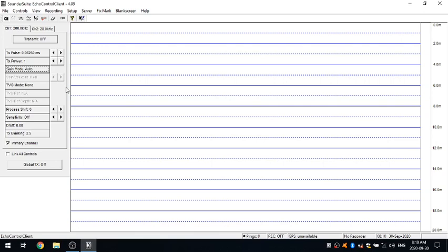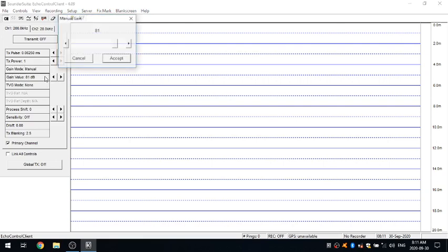Now, we have a range of 0 to 96 dB of gain, and typically you want to have it running 40 dB or less to get a good processing. So if you're running an auto, it's going to reduce it down or increase it accordingly. There is an option if you'd want to go into manual mode, and that may be an area, again, if you're looking at bringing out some more detail of a sub-bottom. You can manually toggle it into manual mode, and then you can use a slide bar and adjust your gain accordingly.